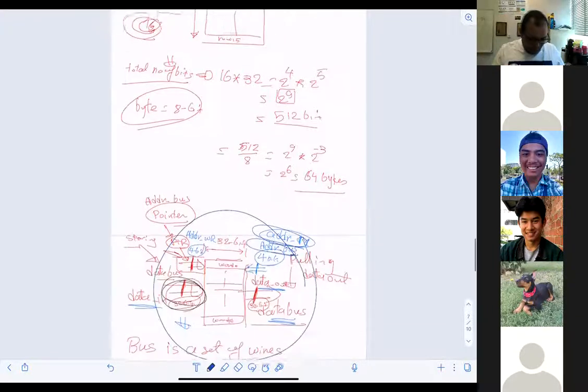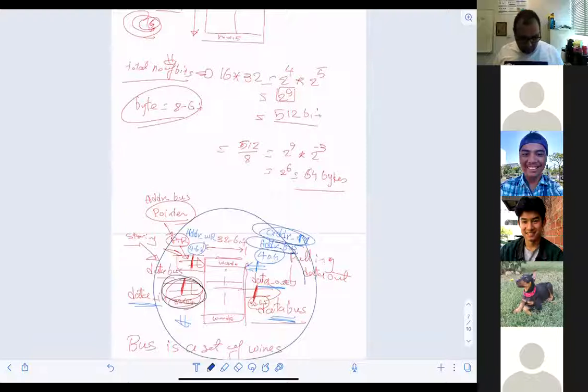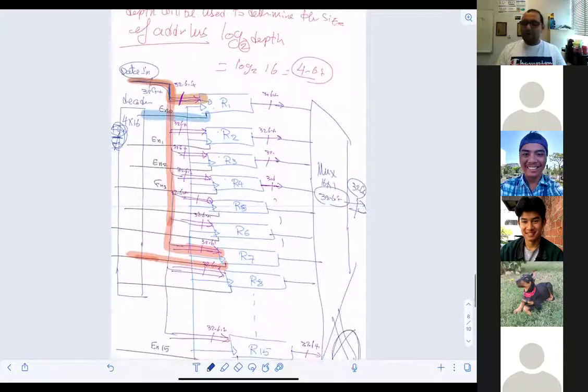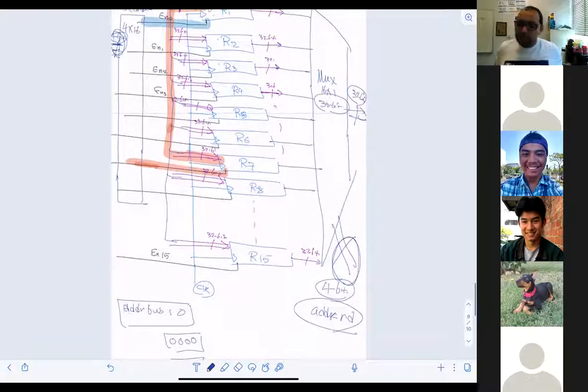Then after that, we made a calculation by hand. We figured out how we can do it in general. Then we defined the ports, as you can see, which are associated with reading and writing. And then we built a very nice memory, with a combinational multiplexer circuit for reporting output, while the decoder controls the flow of the inputs going into the registers, as you can see in the architecture. Do you have any questions?